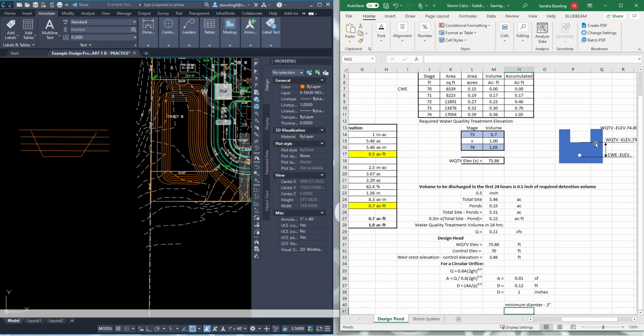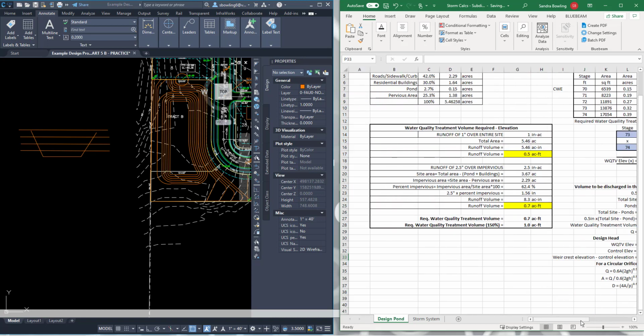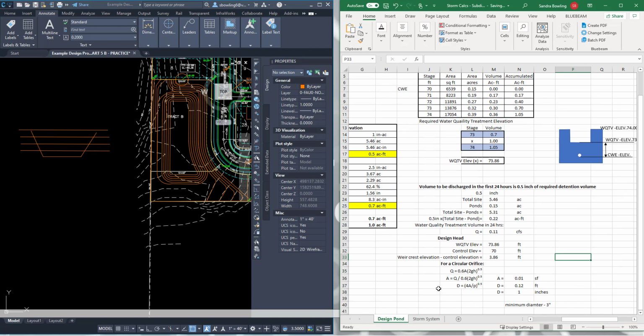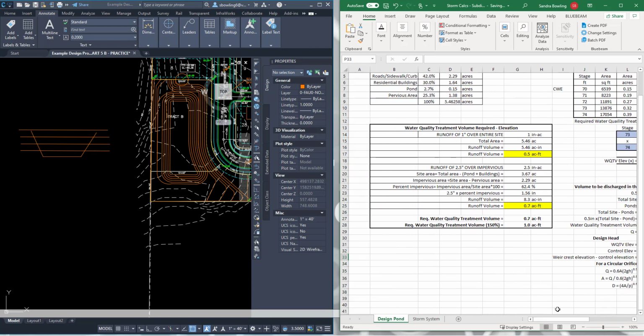And then I'll have to figure out what size weir this will let out for pre and post development discharge. Okay, so you can do a pre-development calculation of what you're allowed out. So if I did Q equals CIA, then I can figure out pre-development versus post-development. So if I had, let's say, and this isn't typically what we use. Typically we use NRCS, but for a quick method, we can use the rational equation.